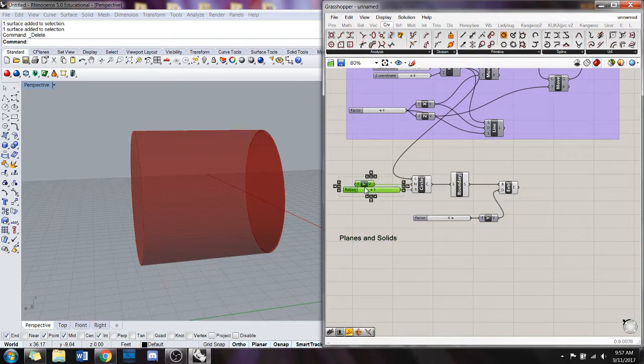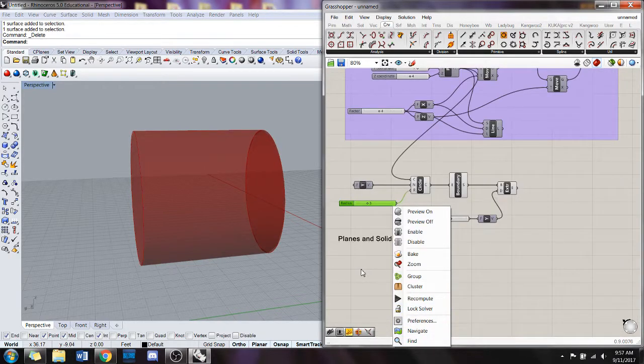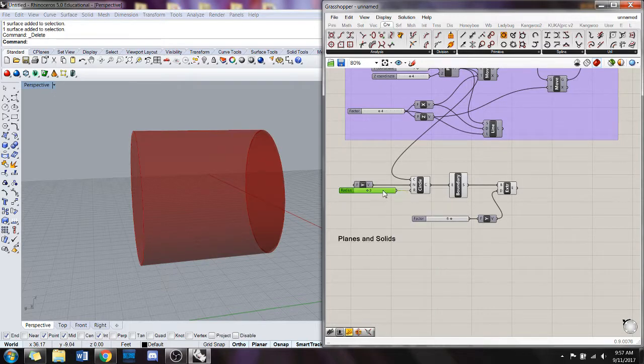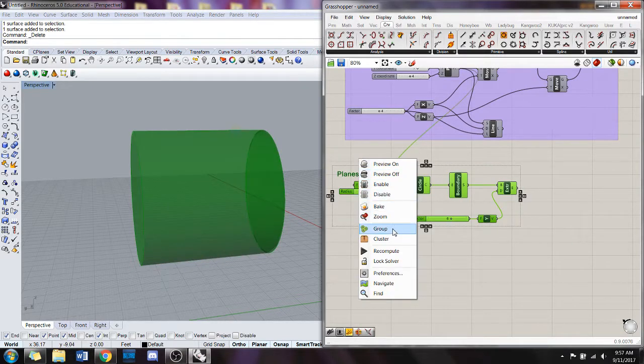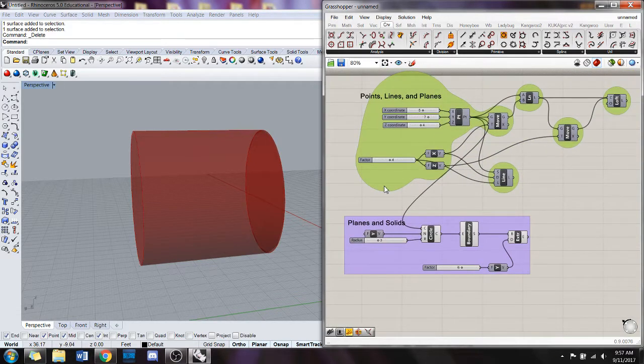Yeah, so I just selected it and then held Alt as I dragged to copy it over. And you can also do a Control-C, Control-V. If you have something selected, it won't give you a paste or copy-paste option in the context menu, so you just have to know that. All right. And a little bit amusing, if you double click on your group background, it's going to change how it wraps to fit the components.